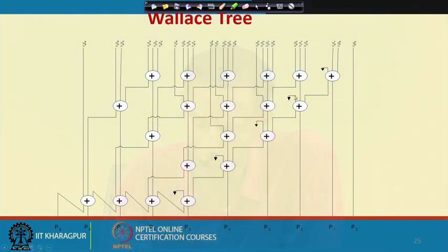Okay. So, here each of these grounded, you see these are nothing but these full adder cells, and this grounded means that one of the input is connected to 0. And at the final stage, I need one 4-bit addition operation, where the carry is basically rippling.